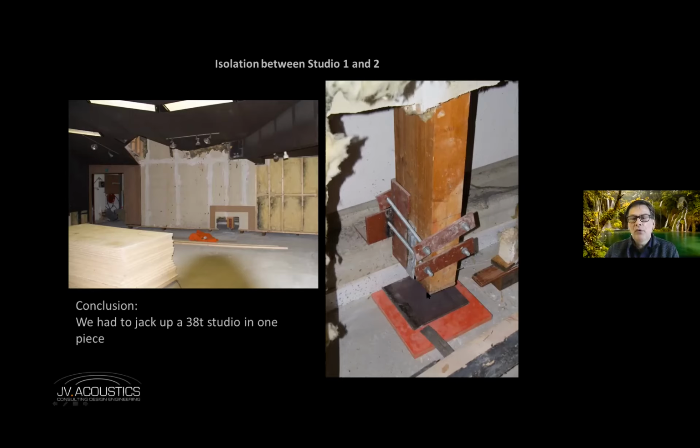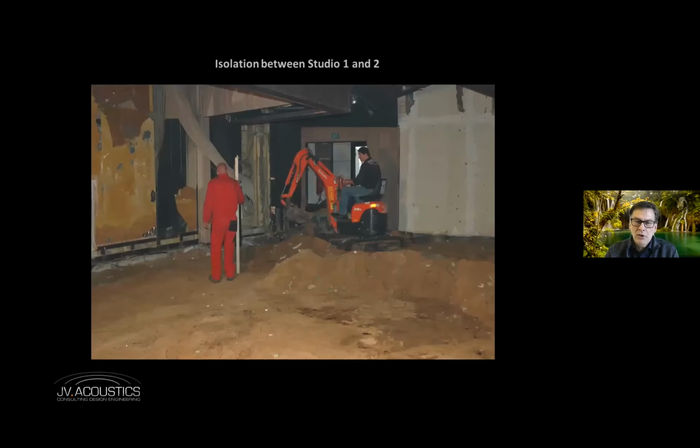And then we put the room back onto those decoupled points. And then we had to dig out the whole ground, dig deeper, put a new primary slab in, and then a new floating floor with a tuning frequency of 15 Hertz. And then everything was quiet.